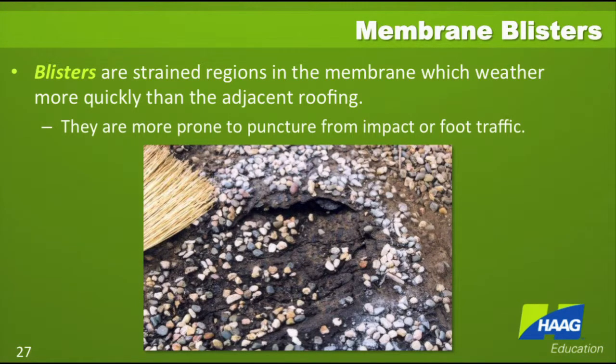You may want to press lightly on it with a foot or with a hand to find out if the blister is intact. Because a blister does not mean there's a leak if the membrane is still complete. But if you press on it and you hear air escaping or you see water squeezing out, that shows you that the blister already has fractured.